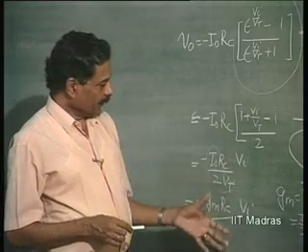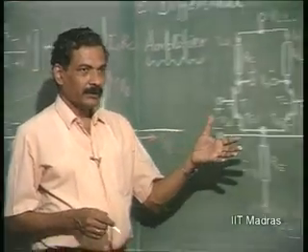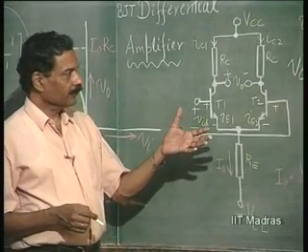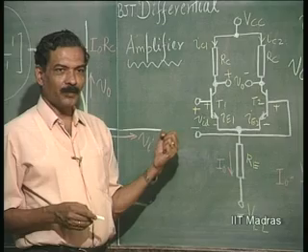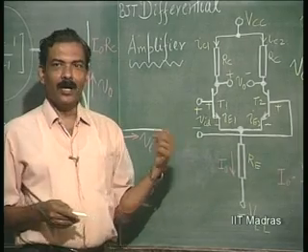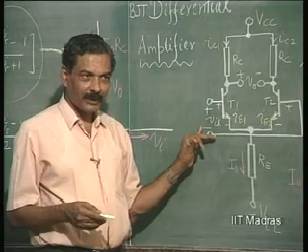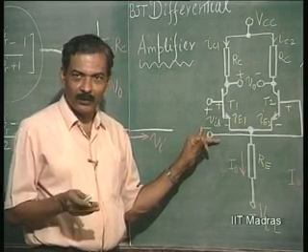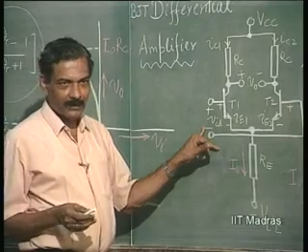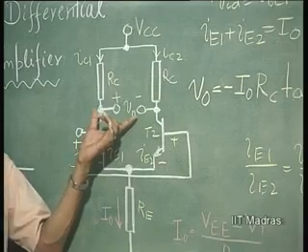However, here we can see that the tan hyperbolic nonlinearity results in only what kind of harmonics at the output? Only odd harmonics exist at the output if I apply a sine wave. Whereas, in the case of a common emitter amplifier, all harmonics are invariably present. How is it obvious for us here?